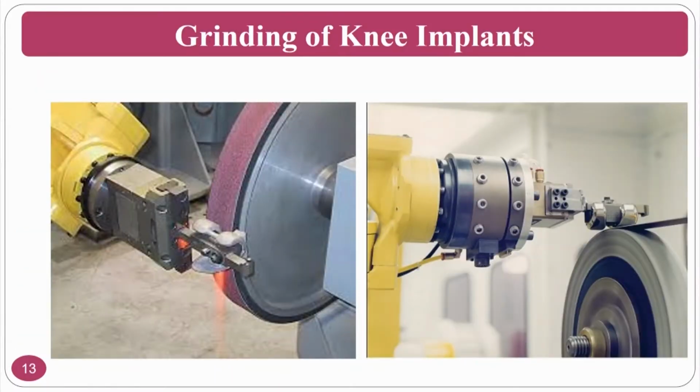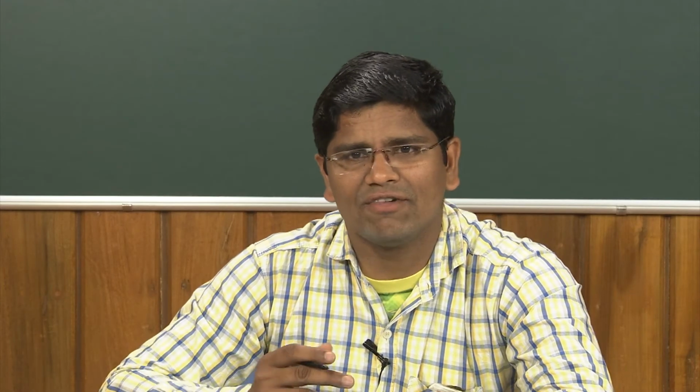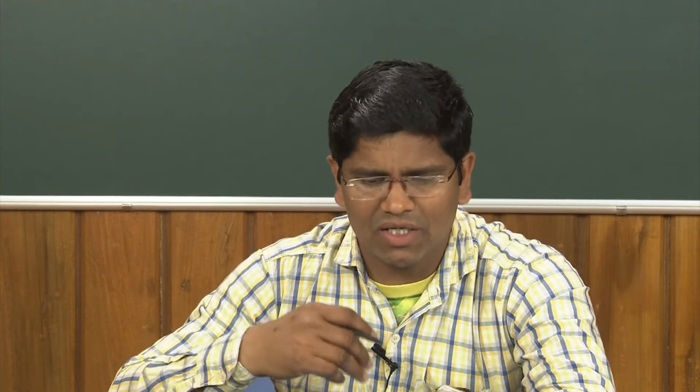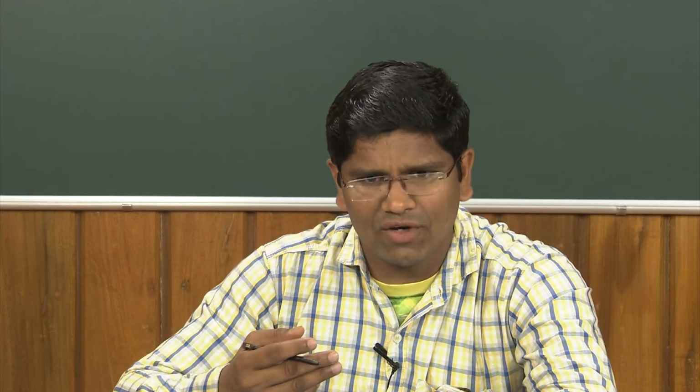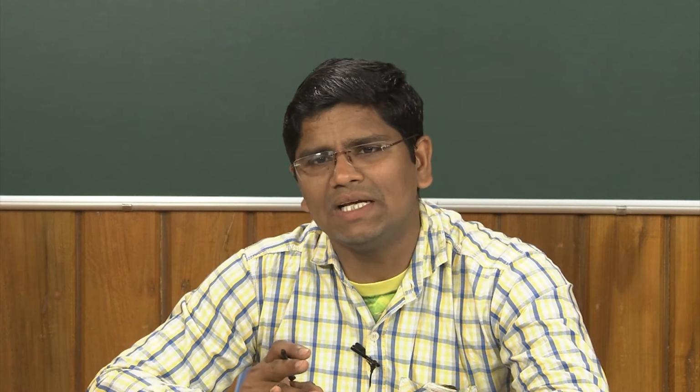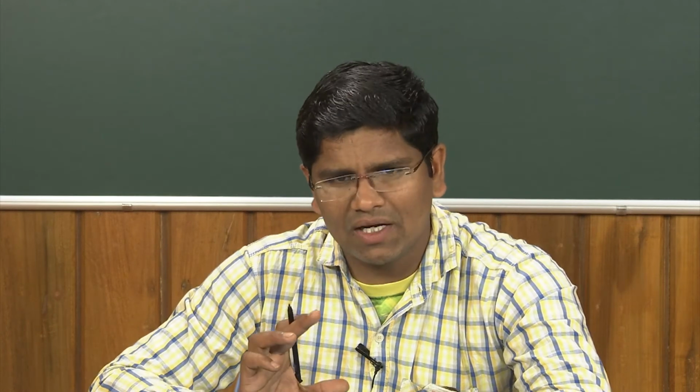At the same time, if you want to fabricate the knee implant at a minimal price, you can go for belt grinding or buffing operations also. Okay, so for advanced finishing processes like what I said, MRF or magnetorheological finishing or ball end magnetorheological finishing, assume that these are going to be costly for you, then you can design your own belt grinding process like what is given here. You can go for this type of process also. That means you are going to do the machining process, then the profiling, then the finishing operation to make a knee implant.